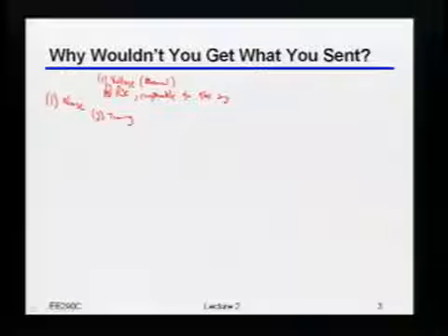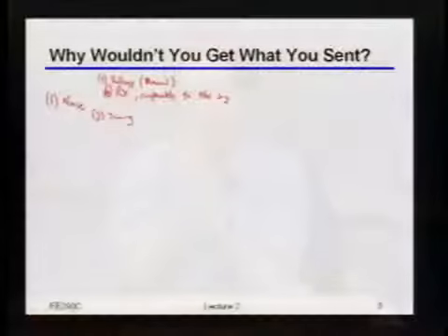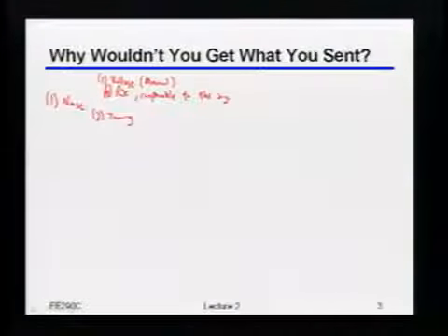What else might actually matter? What other kinds of things can sort of mess you up and make it so you get the wrong bits on the other side? ISI. Okay, you said ISI. We'll come back to that one in 1 second. Oh, you're going to say the same thing. Okay, so what does ISI even stand for? Inter-symbol interference. Okay, yes, you said it's inter-symbol interference. So I want to just slightly generalize.